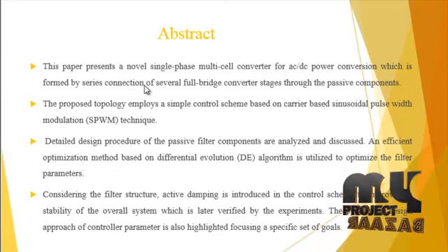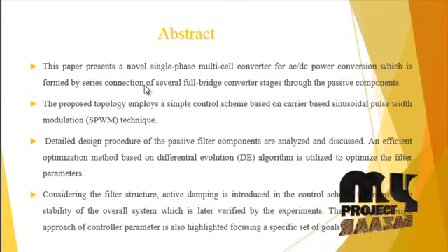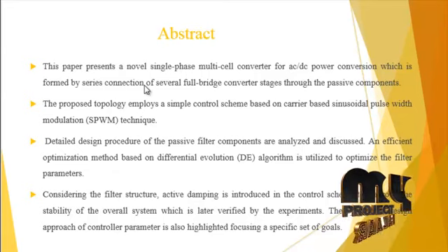The proposed topology employs a simple control scheme based on carrier based pulse width modulation technique. The detailed procedure for passive filter components is analyzed and discussed. An effective optimization method based on differential evolution algorithm is utilized for the optimization of filter parameters, considering the filter structure. Active damping introduced in the control scheme improves the stability of the overall system, which is later verified by experiments. The symmetric design approach of the controller parameters is also highlighted, focusing on a specific set of goals.